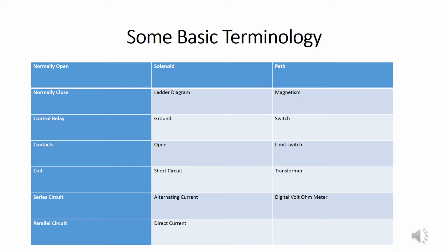A ladder diagram is an electrical diagram that looks just like the rungs of a ladder, and they are read from top to bottom, from left to right. Numbers are used to show where connections are made, and emblems or symbols appear between the rungs to tell the reader where the power is going, how it will be controlled, and ultimately how the circuit operates.